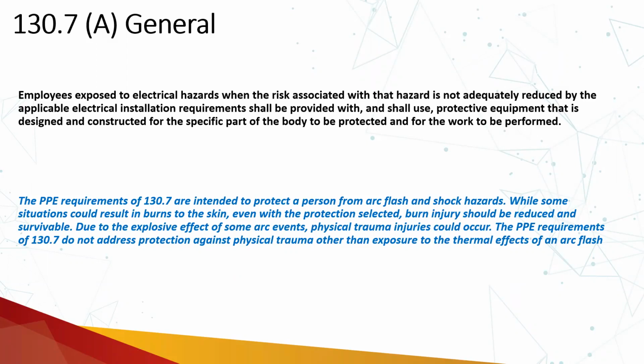Because we know that during an arcing event there are some poisonous gases, or huge pressure waves are released, which can cause harm other than skin burn. Those types of things are not covered by 70E.